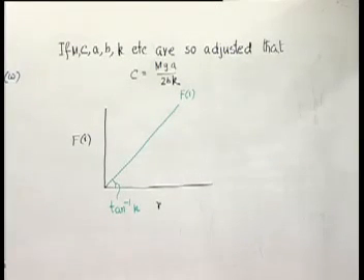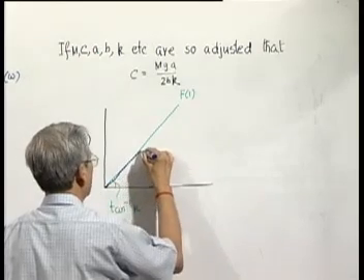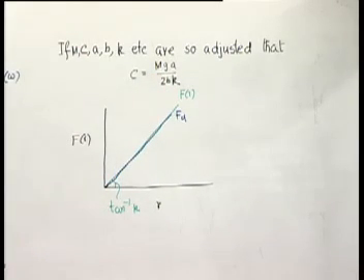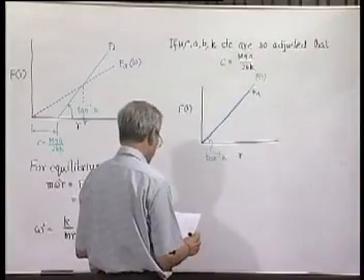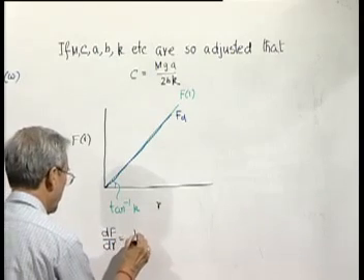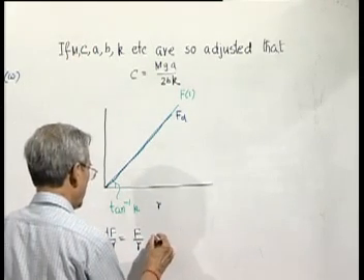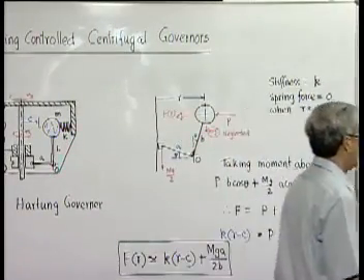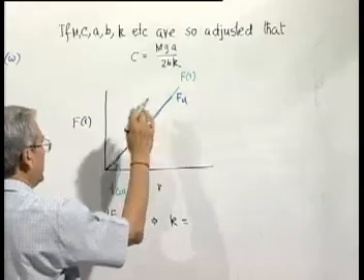So what does it indicate? That the system can have equilibrium condition only if the deflecting force also coincides with that, and that indicates, we have already seen, this kind of situation is called isochronous situation, or the governor is isochronous at this speed. So we find that dF/dR equal to F/R was the condition for isochronism, and dF/dR is nothing but K, and F/R is equal to, F is equal to Fd at equilibrium, which is m omega square r.